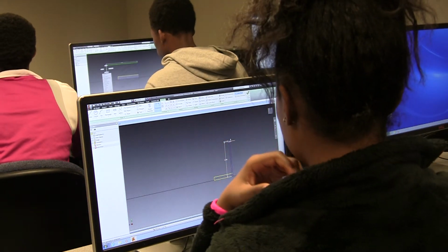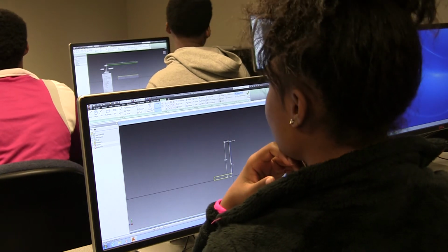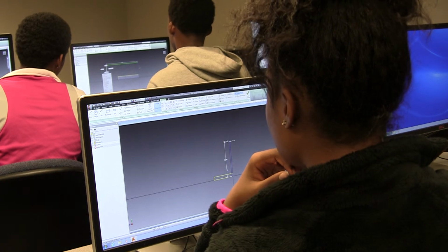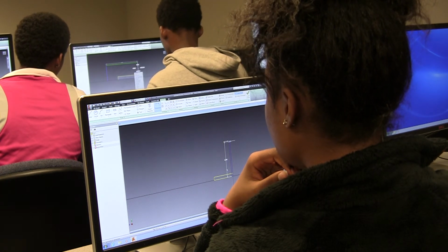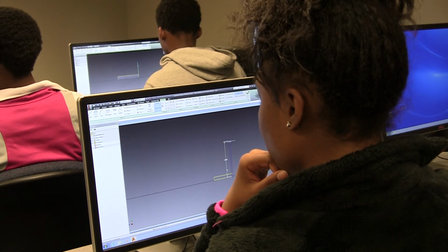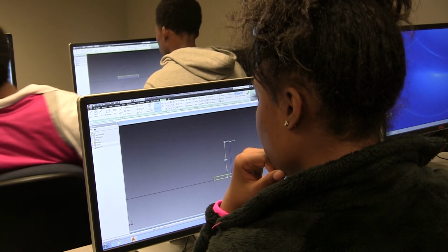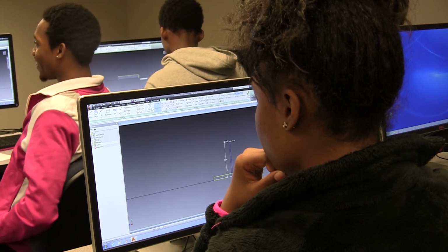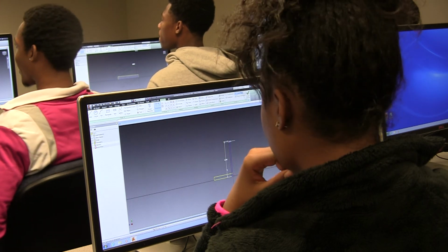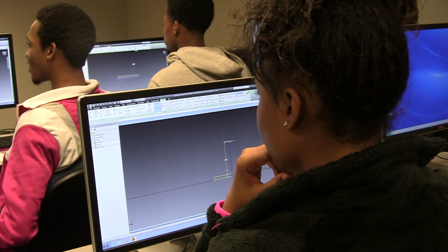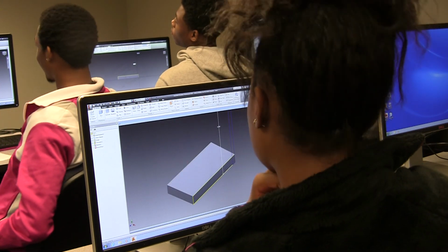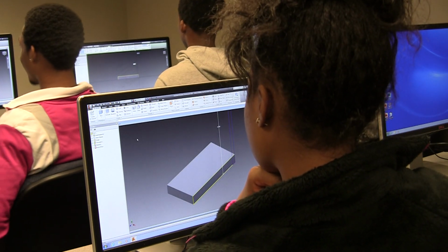I'm gonna stop here until everybody gets it. After you're done drawing the shape that you wanted to draw, what do you do next? After you're done drawing what you want to draw, what do you do next? Anybody? Finish sketch. Click your green check mark for finish sketch. If you want to change the view, I want you to